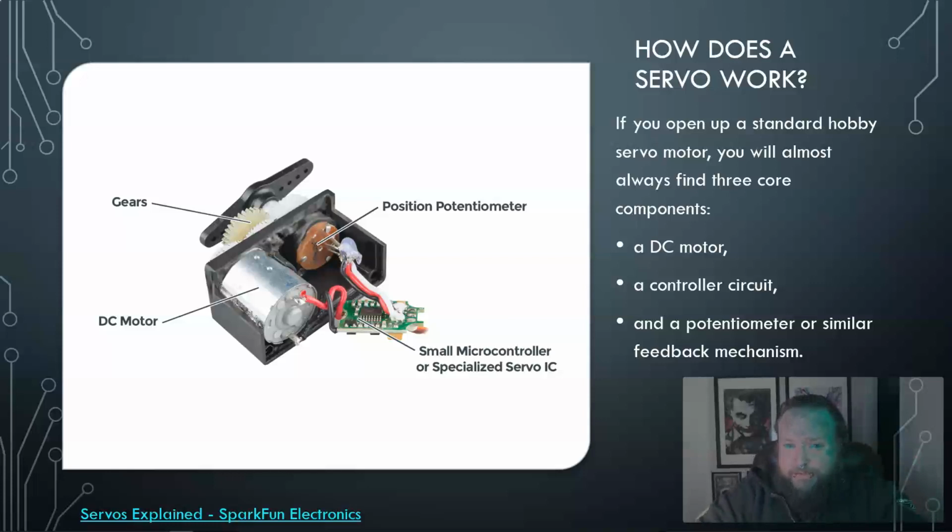And that's multiple servos. When you saw that hand, really they had a different structure and they were recreating the idea of tendons. So there wasn't something individually controlling each knuckle in the finger. There was just a hinge and a string, and when the string or elastic is pulled, like your tendons in your hand, they react. And then it was servos that were controlling it. Same as the little gripper arm, which is a very common model that I've seen kits for online and for 3D printing the pieces.